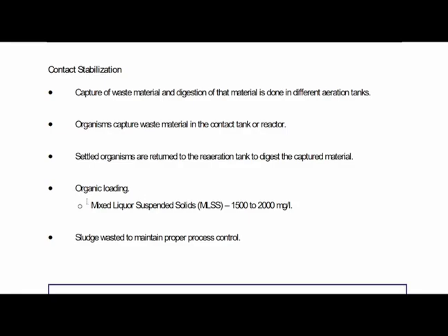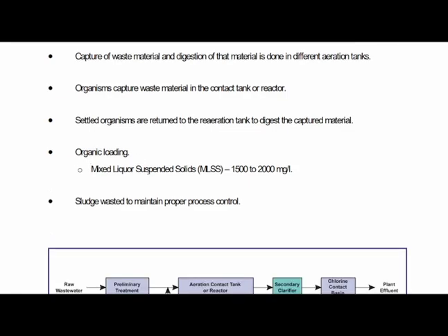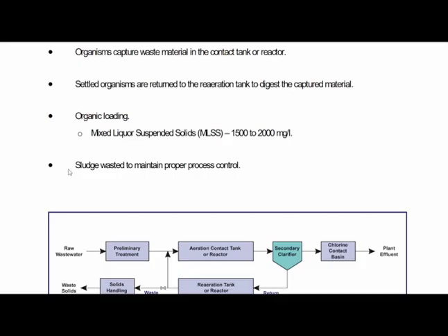Organics loading: mixed liquor suspended solids, or MLSS, 1,500 to 2,000 milligrams per liter. Sludge is wasted to maintain proper process control.